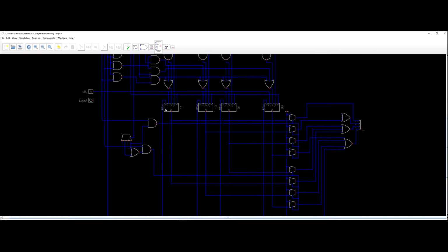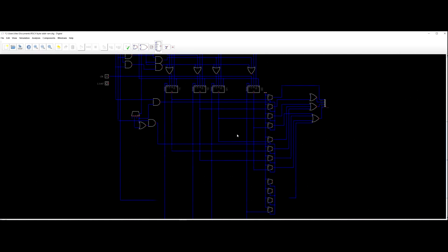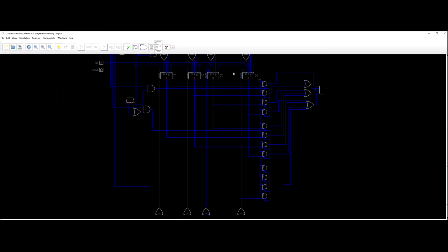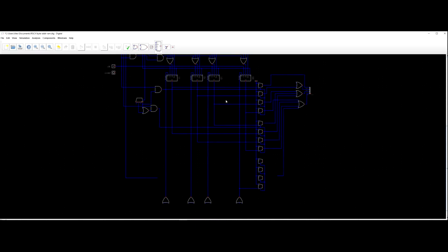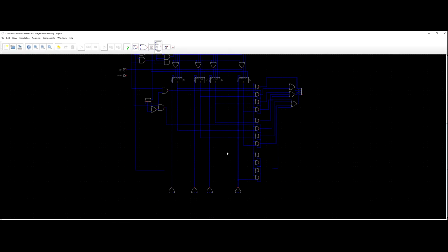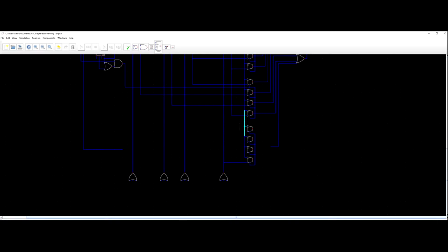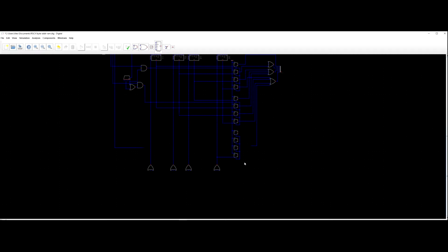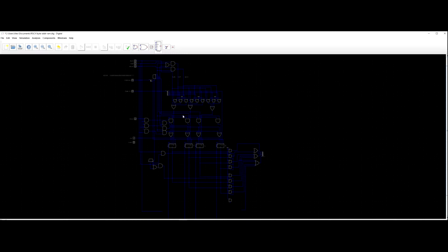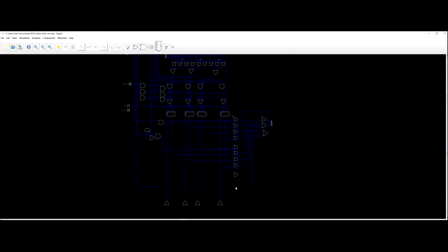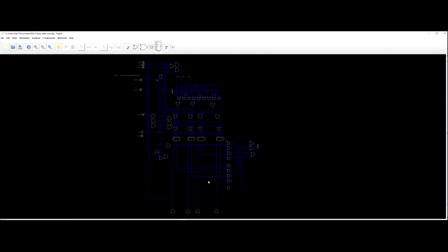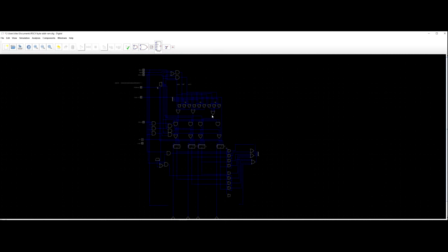Right, when I send the load signal in, it would only load one at a time. The other ones would be in high impedance states, so they wouldn't backflow and interfere with it. So I should be able to just OR them all together and use a single mux. So now, yes, so 8, 9, 8, 9. See, that's that. I knew that. I was wondering why we have more than we need.